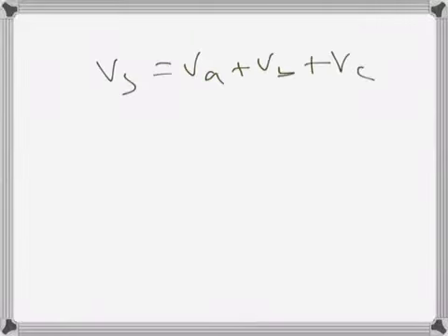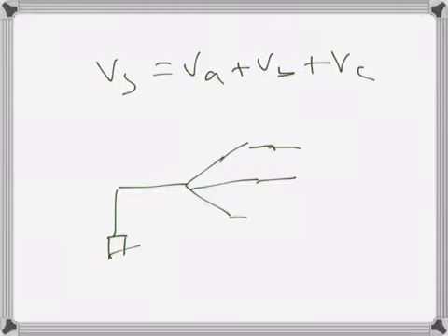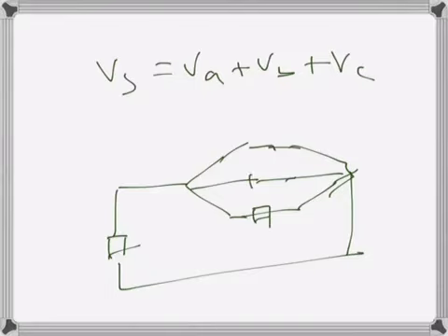So basically Kirchhoff's voltage law is coming from the conservation of energy law. Now there's another thing, conservation of charge. So the other law is Kirchhoff's current law, which says that if in a circuit we have several branches, at some point, let's say the circuit is something like this, there's a source and there are a few branches there, and they probably meet up somewhere here, and then they come back here, and there are elements there.